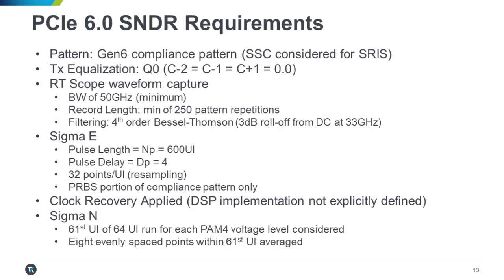And just focusing on the PRBS portion of the compliance pattern for sigma E, so not inclusive of those low frequency sections. The clock recovery that gets applied is not explicitly called out, so it's really DSP implementation specific.